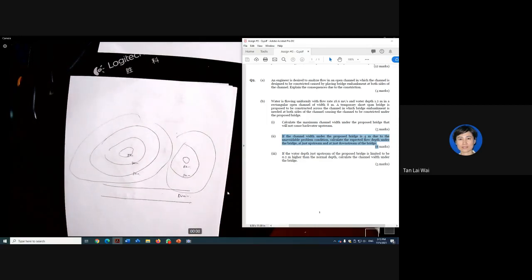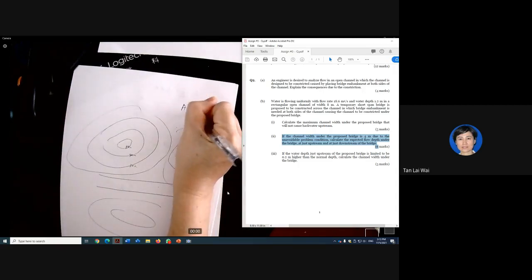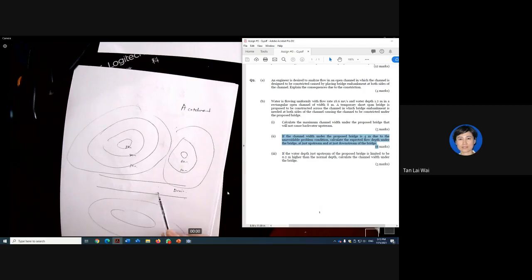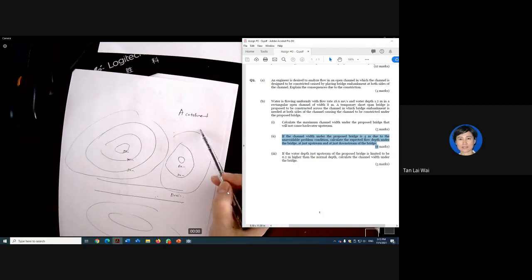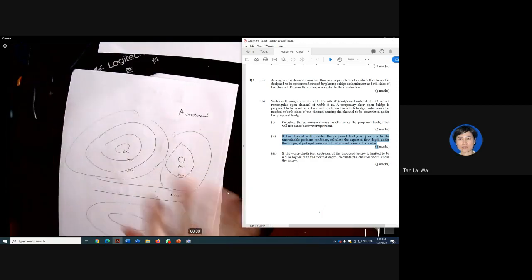Now, actually you have to look at both sides. If you ask me how much water or A you are going to consider, the A of catchment, the catchment area. Because the A for Manning, you are going to get it from the cross section of this drain. For the rational method, what is the flow? What is the catchment area? Imagine this is plan view.